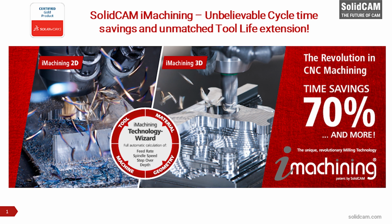My personal preference, and what I've done for many, many years, is I try to target between 40 and 60% spindle load as a maximum. And that way I'm never damaging the spindle, I'm never hurting the machine, and yet I'm getting extreme performance out of it.